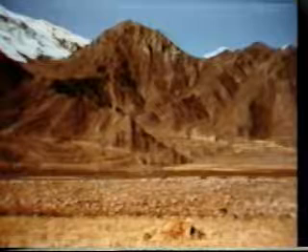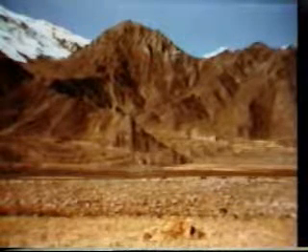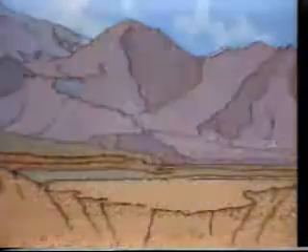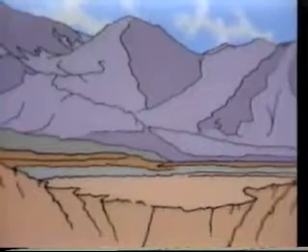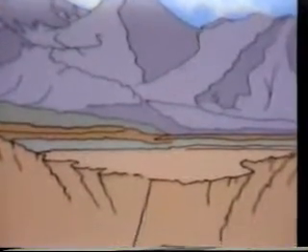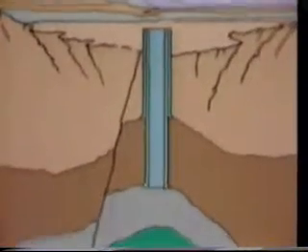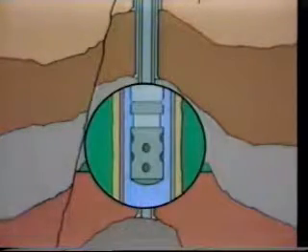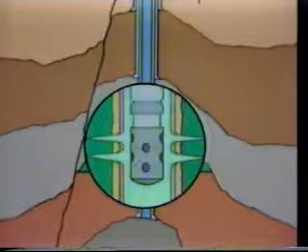We remember from module GL301 that as we drilled our well, we added several different strings of casing to support the hole, control pressures, and prevent fluid communicating between formations. The conductor pipe, surface pipe, and production casing strings were all cemented in place. The production casing string was then perforated over a selected formation interval.